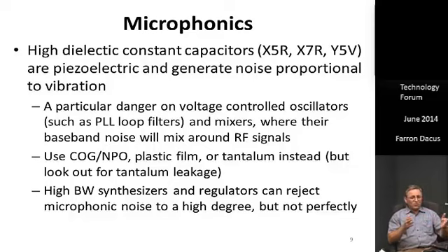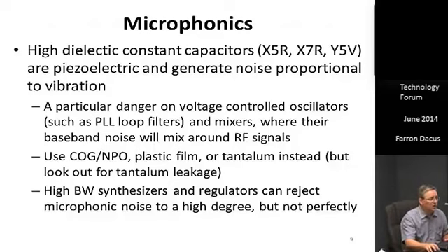But if you're shaking the capacitor in the RC, if you've got a 1 microfarad X7R cap hanging there, you might find that generates tens of dBs of visible noise on that VCO. So the answer there is use low noise supplies to start with, actively low noise, and then use these C0G type caps when you can get away with the small capacitance. When you need more capacitance, go to tantalum or film. Don't go to the high dielectric solids.